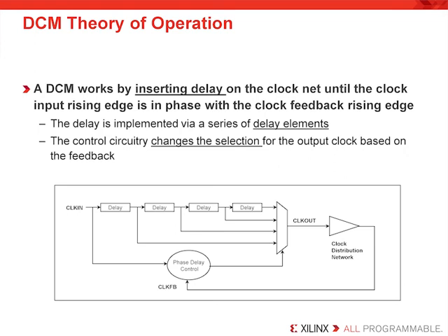The generated clock has all the same attributes, including a frequency and jitter. These adjustments will create additional jitter on the output clock. So one important thing to be aware of is that the synthesis and the implementation tools should automatically calculate and adjust for this extra jitter during timing analysis so that your system can tolerate that.